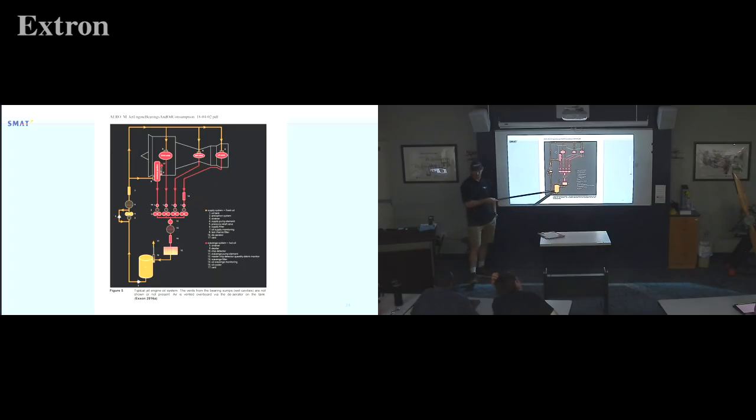So is that a hot tank or a cold tank? Cold tank, which is our common one. So scavenge pumps through our cooler into our tank, and then we have our pressure pump that is going to be sending oil back out to our bearing assembly. What's this little guy here, do you suppose? Oil relief valve. Yeah, like an oil regulator or oil relief valve. So anyway, that's just a standard little turbine system, and mostly it gets you to go, okay, I know the difference between a scavenge pump and a pressure pump. Like I said, I'm trying to make this last exam pretty easy on you.